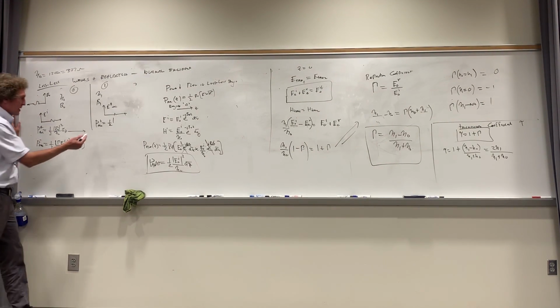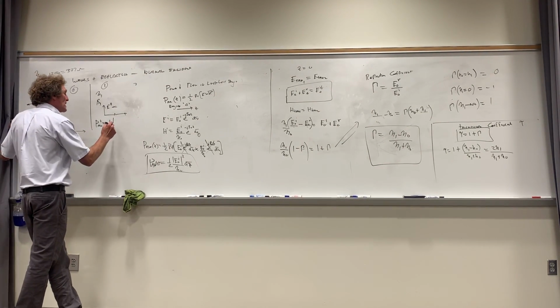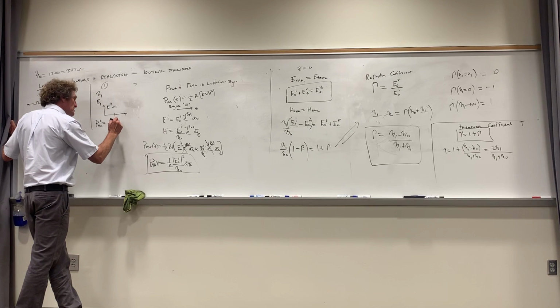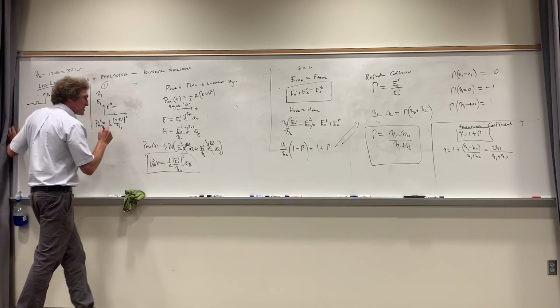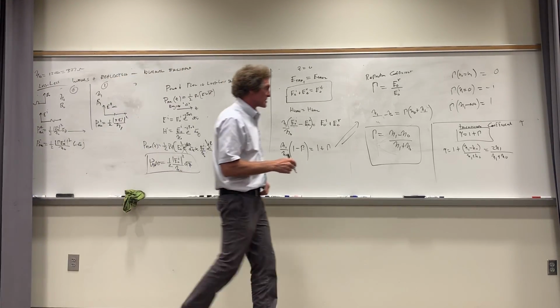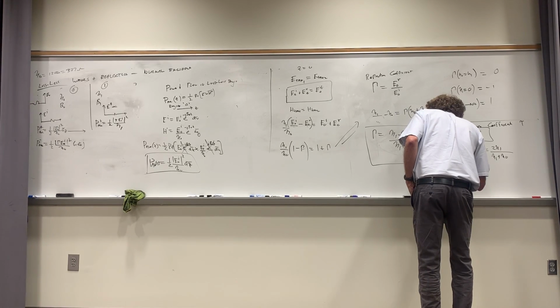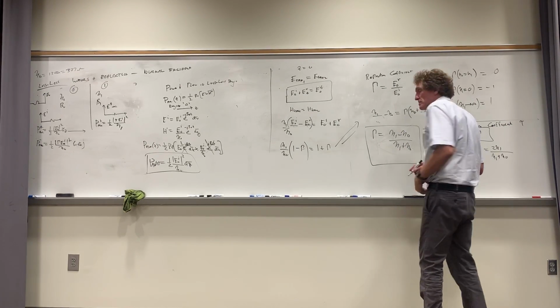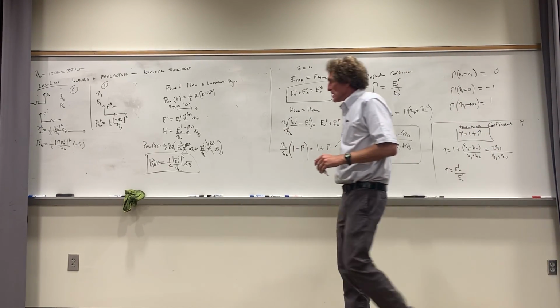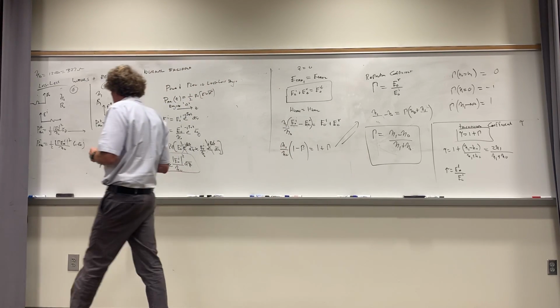All right. How much power is flowing here? It would be 1/2 the magnitude of the transmission coefficient times the incident field squared over eta in region 1. And this is something I didn't say, but I should have, but the transmission coefficient is the ratio of the transmitted electric field over the incident electric field. Are you with me? Now take a look at this, and it's important you see this.